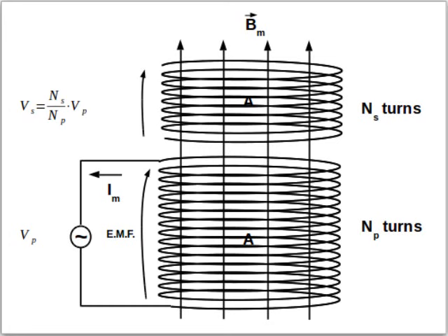We make the changing magnetic field generated by the primary go through the other coil that we are going to call the secondary, and this will produce exactly the same voltage per turn, producing a total voltage that will be proportional to its number of turns. Up to now we have half of the magic.